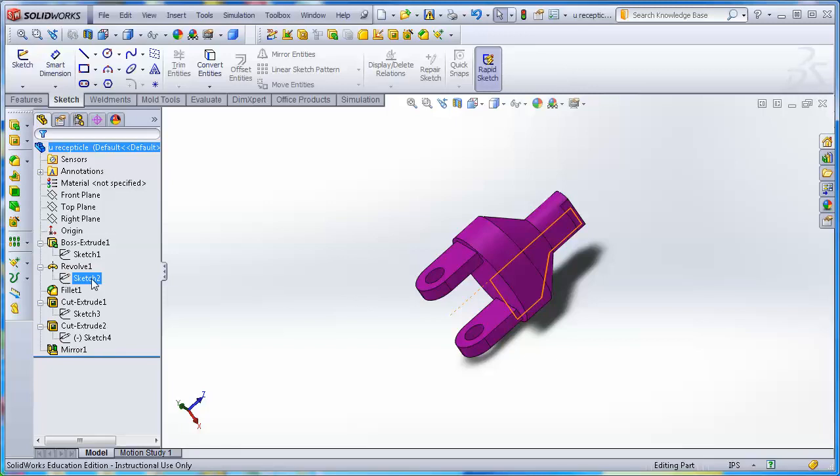And so sketches followed by extrudes, revolves, etc. will be prime ways of creating geometry. To document a part, we want to see the sketches, and then finally we want to see the geometry. So here's how we would want you to document a part. We have just brought the part in, we've done nothing to it. I've expanded all the plus signs in the model tree.